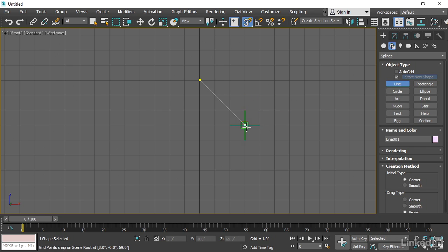If we want to, we can create a curve at the same time as we create the point. And that's done by clicking and holding the mouse down. So I'll do that. Click and hold the mouse button and drag around, and we're getting a curved line. And this is known as a Bezier curve. And the location of my cursor is the tangent handle for that Bezier point. And we'll see more about this later. When I release the mouse, I've now created that second point, and now I just want to create the third point. So I'll go down here somewhere and click to create another point.